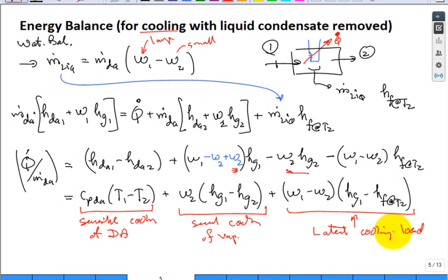Even though I put heat into something, it didn't change its temperature. It kind of hid the heat by not changing the temperature of the substance. Often that's associated with vaporization, or if I remove the heat transfer out. It didn't change the temperature, it just changed the phase.